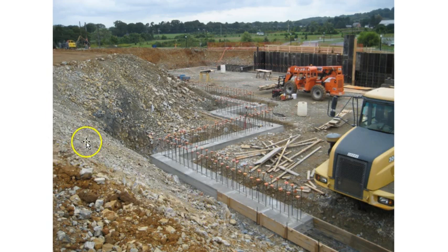So this is not a particularly stable soil, so we have a very great incline to this. There's a lot of rubble in it, so maybe rock had to be blasted out. So one issue we talked about when it came to soils was what's required to happen now that we have this littered with what appears to be fragments of rocks. Does it need to be cleaned out and screened, or is it suitable to be used the way it is? A question the earthwork contractor wants to know beforehand.